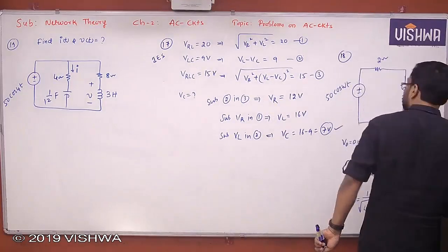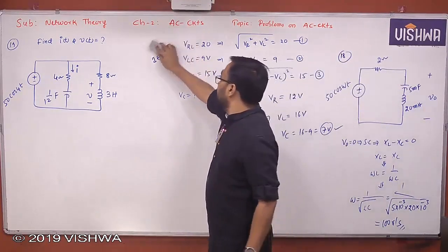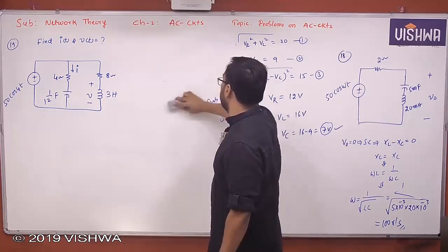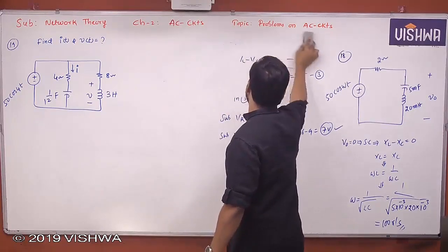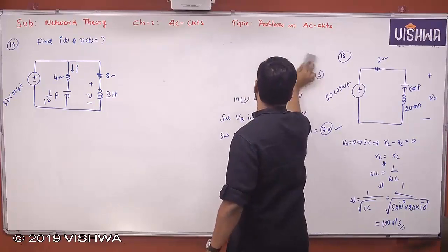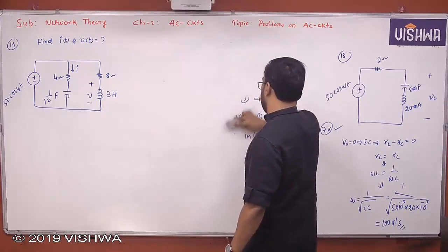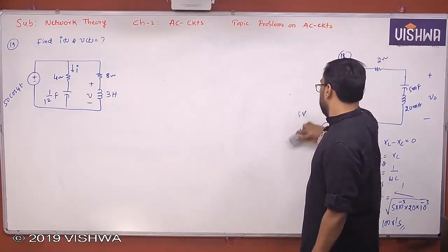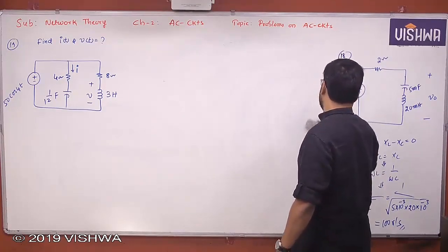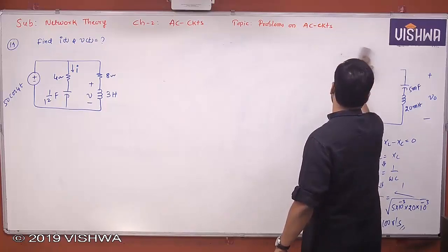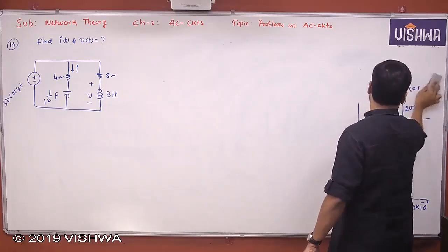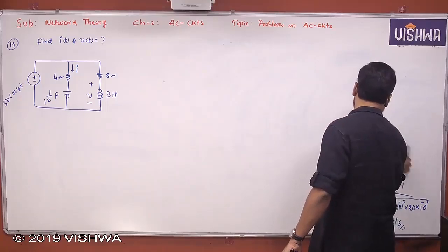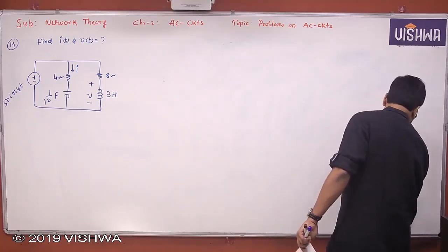See, whenever an AC circuit is given, remember all of you, first of all you need to convert that circuit. Whenever an AC circuit is given, first of all, you convert that into complex form or phasor form. Understand? You can't deal with the problem in the time domain. Some few cases can be handled, but let us not take any risk. All the time, better we have a common practice that we convert into what? Complex or phasor form. So you know that already.